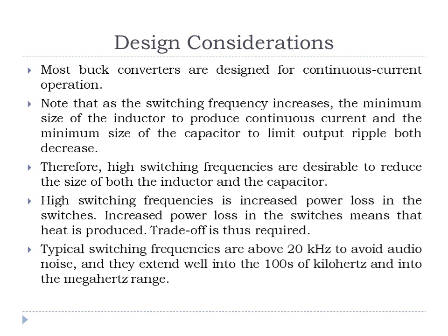So some trade-off is required to select the optimal value of switching frequency, and usually a frequency greater than 20 kilohertz is selected to avoid audio noise. It can extend up to hundreds of kilohertz and even in a megahertz range. So using all the expressions which we have discussed, you can practice some questions which are given in the next slide. Thank you.